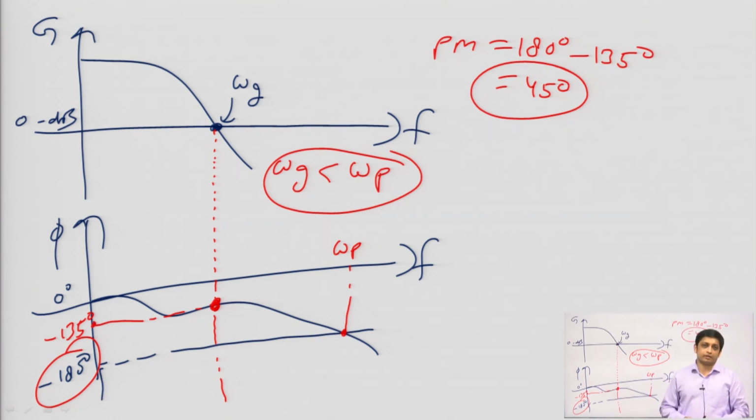So, the point is that if we are designing any multi-stage amplifier, we need to check the stability, because there are comparable poles and zeros and it can degrade the stability. Your phase margin may be positive, if you are getting plus 2 degree, plus 3 degree, it is positive, but that is not the sufficient phase margin. The optimum value of the phase margin is approximately 60 degree. So, we want sufficient and optimum phase margin, right, for better stability.